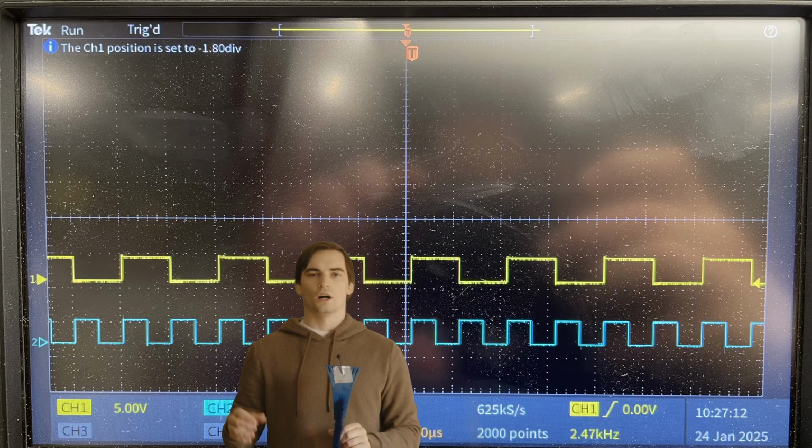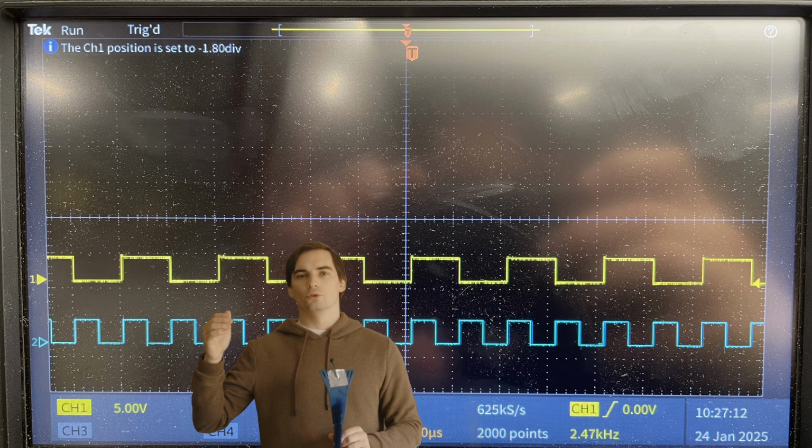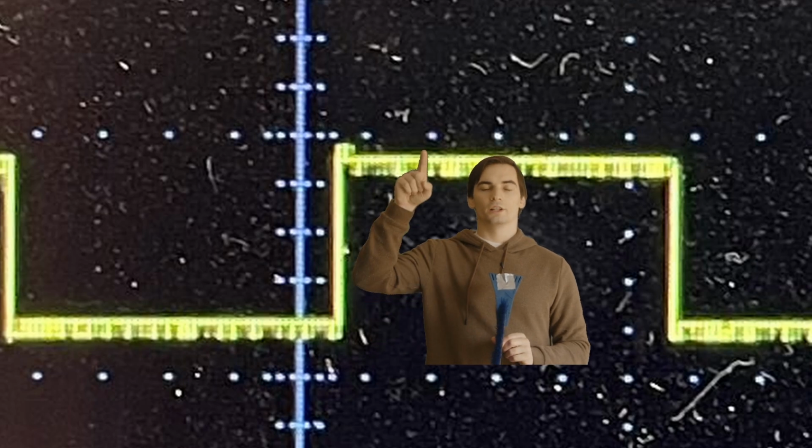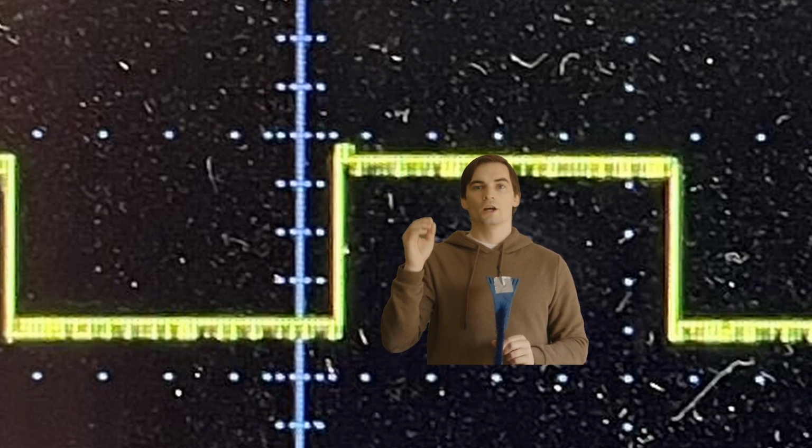So since I didn't have any onboard hardware to communicate with this chip from my Arduino, I had to resort to what's called bit banging, which sounds pretty intense, but it's a lot less exciting than it sounds, unless you're kind of into slow and inefficient communication. Essentially what that means is we're just manually turning a line high and low or putting electricity through it and turning it off, again, manually to send messages to the chip and receive them. This shouldn't be too much of a problem. It actually was a good bit of a problem.